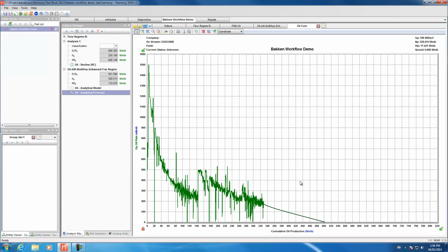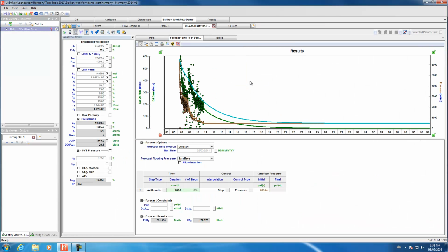One thing I want to talk a little bit about now, though, is this model has been done analytically. And because it's analytical, it will tend to be pessimistic in terms of fluid flow in the reservoir, purely for the reason that we assume that it's single-phase oil throughout the production history. In reality, there will be some solution gas that comes out either during the history or later on in the forecast that will provide some pressure support.